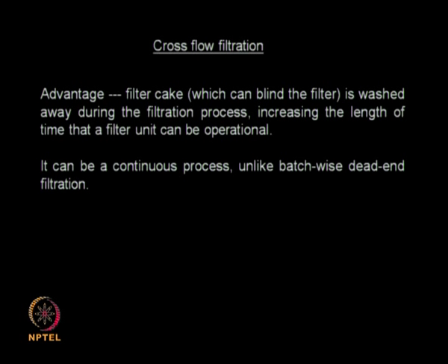So in a normal dead end filtration, after some time you need to remove the solids, that means it is a batch process, whereas in a cross flow filtration we can do it as a continuous process. So that way I can prolong the filtration time. That is the main advantage of cross flow filtration, but there is one disadvantage